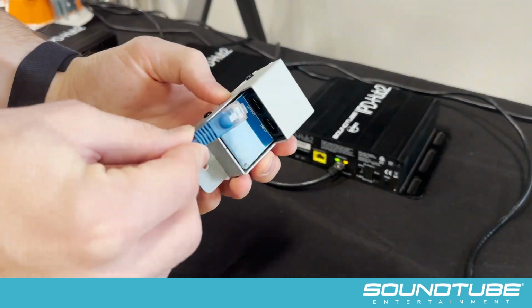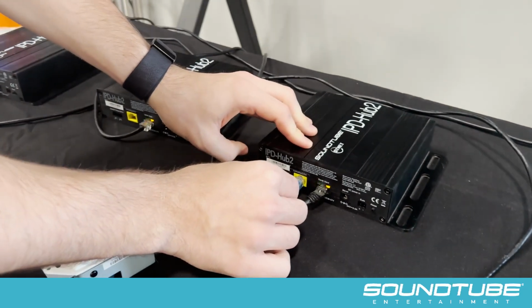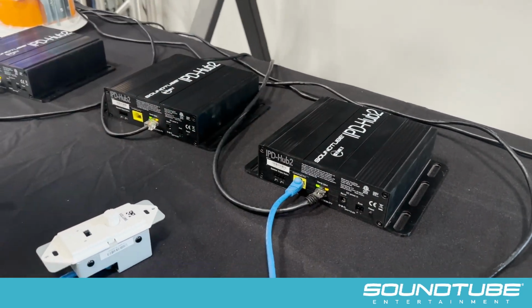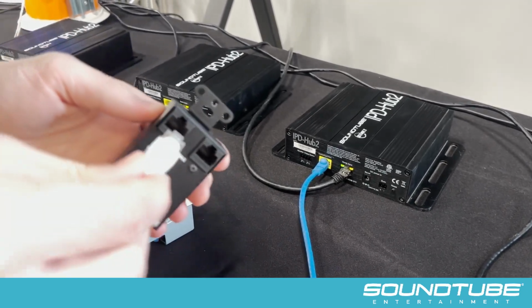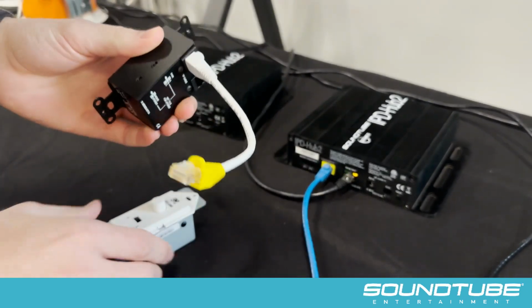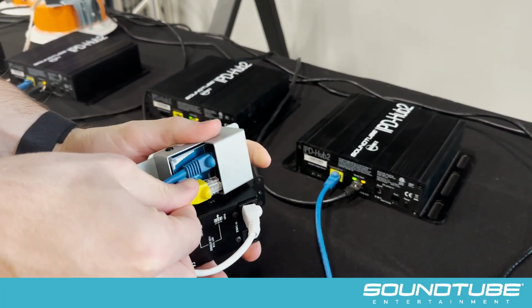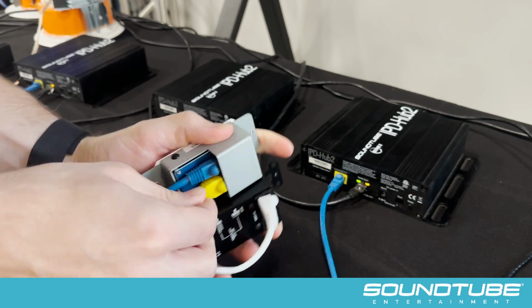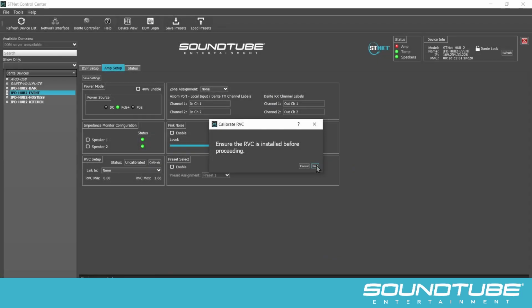This one's a little different. First, we plug our RVC in directly to the Hub 2 with the network cable going from the RVC's output connection to the yellow input port on the Hub 2, and then we will use an RDL Format A sender to pass our local audio through the RVC to the Hub 2. This requires use of a special cable provided with each Hub 2. We'll go through the calibration process like before, and then save the settings.